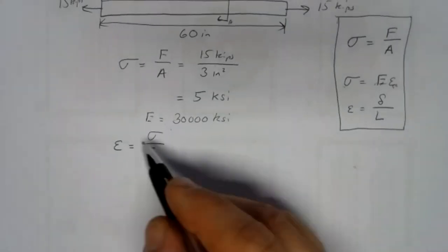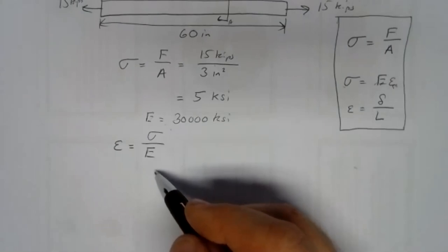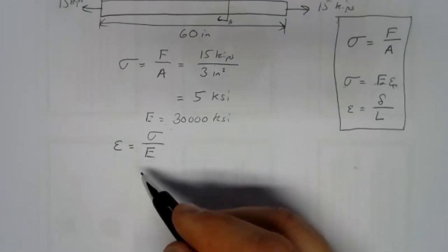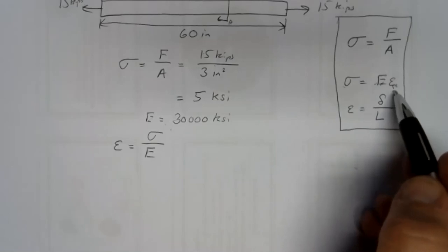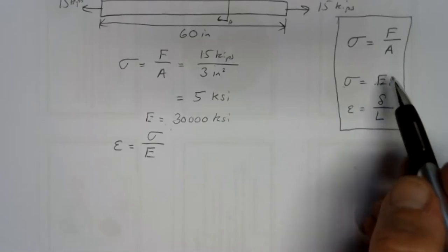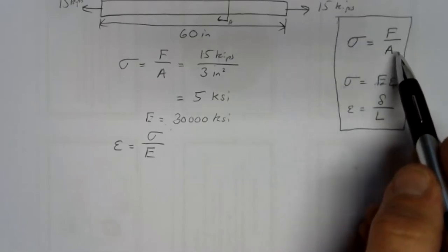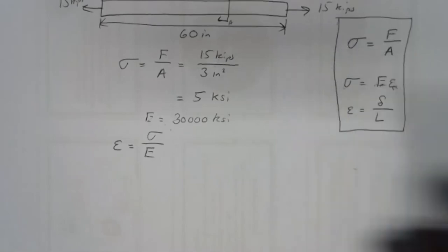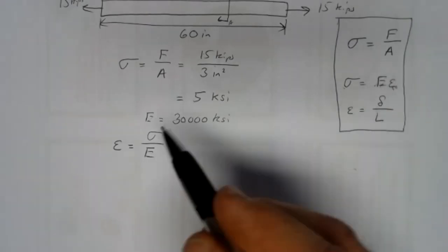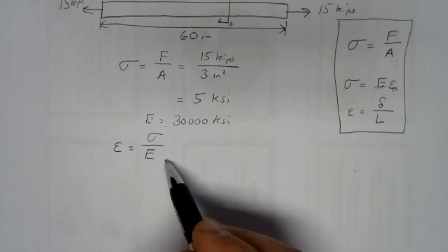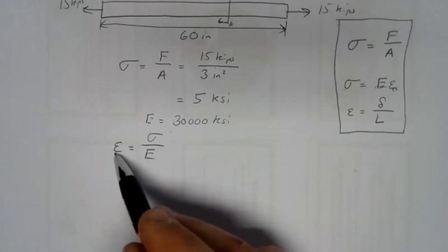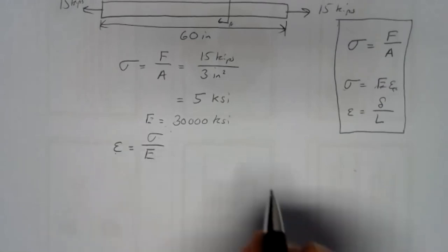And frankly, that's a better way to write it anyway. They only write it out on one line because it's easier to print that way. It's closer to the definition. It would be like taking the stress equation here and saying force equals stress times area. It's not as informative a way to write it. So I'd probably write Hooke's law kind of like this. What I get, the strain, is stress divided by Young's modulus.